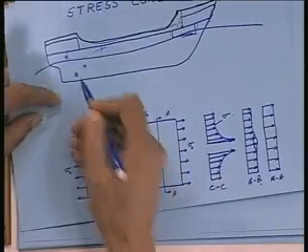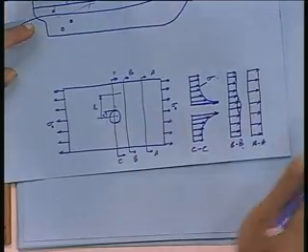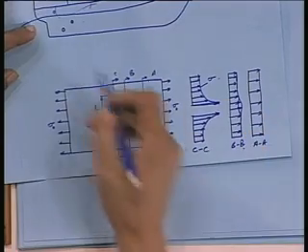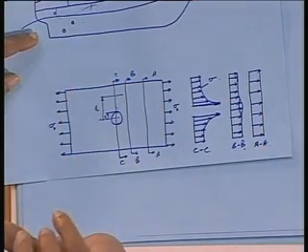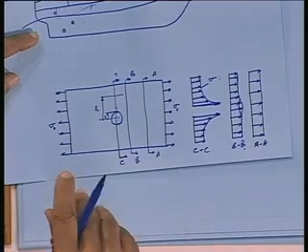Continuous process. Now these holes which we make will be subjected to this stress concentration, and therefore for the compensation of this we try to strengthen them by putting a ring sort of a thing. We can say that the pipe which is welded there itself will act as a flange, but again we cannot be 100% sure on that side. So we put the pipe from inside, but from outside also we try to put a ring sort of a thing. So this part is different.